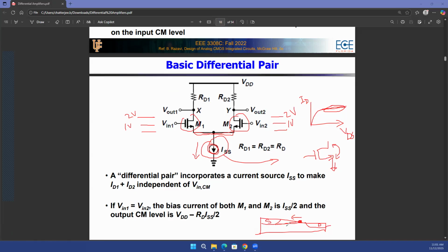So let's say your length is very large. Let's just assume an extreme case. Let's say you have a 1 mile long transistor. Now, by changing the drain to source voltage, you'll basically change the length of the channel, or that pinch-off point, only by, let's say, a few nanometers or micrometers. And that does not even count, because your length is as large as a mile.